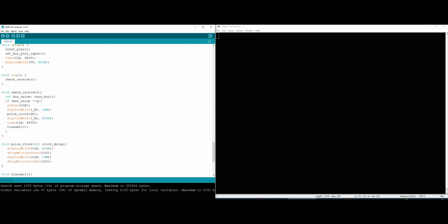So we are just reading the bus, and we're checking if that value on the bus is 0 or not. If nothing is sent and there is no data on, let's say, our receive line, then our bus will be 0 because there is no data on it. However, if anything has been sent through UART, then that data is going to show up on our bus, and that's what I'm checking here. If it's not a 0, that means we have a value on the bus, and at that moment I'm turning off the main clock for the whole system.